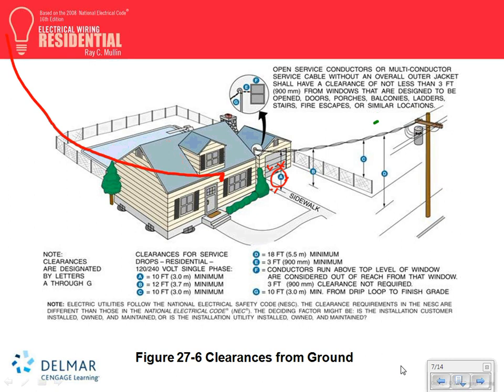The minimum conductor size that you can use for service is copper or aluminum, 8 or 6. Obviously, 6 is going to be the aluminum. For both of them, overhead or underground, the minimum that you can use is number 8 copper and number 6 aluminum. Very important. These are for the service entrance conductors coming to the building. So they give you the minimum, guys, that you can do. I want you guys to go to page 71 because it's really important. Page 71.